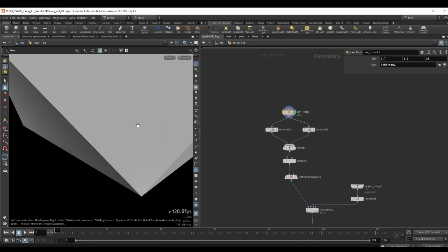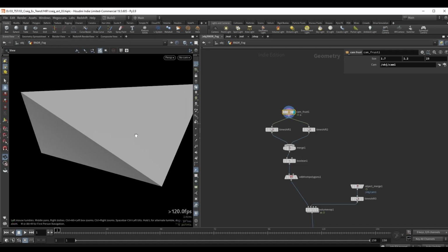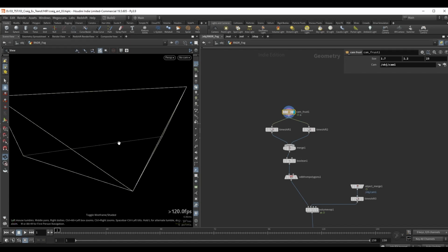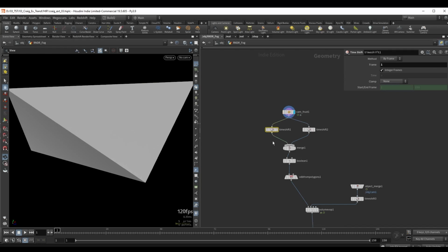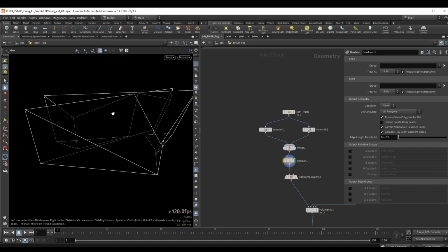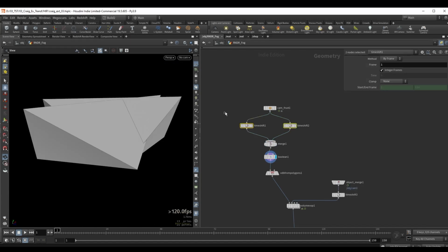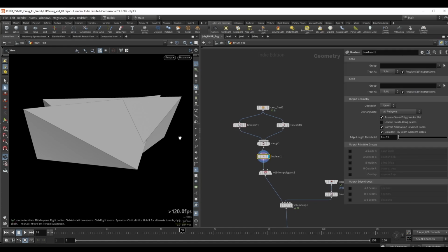that I created, and I will also include this in the downloads if you follow the download link in the description, which is just pointing to a camera and it's creating a geometry based on what the camera sees. So we are freezing this at the beginning of the animation and also at the end, and we are now using a Boolean union operation to get rid of any inner intersections between these two objects. So by combining these two time shifts, we are going to cover the entire area that the camera sees at any given frame. And we don't have to compute this each frame.